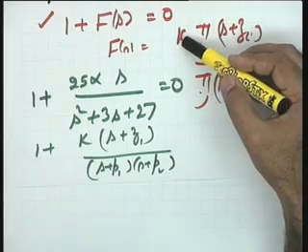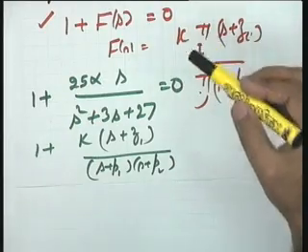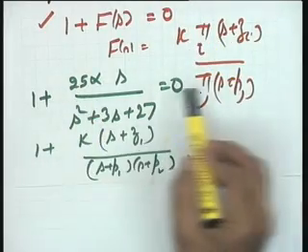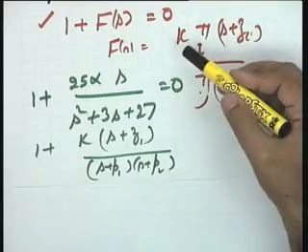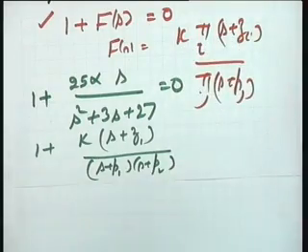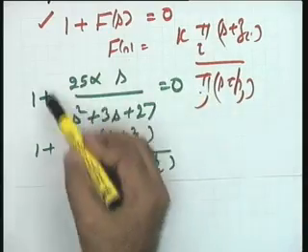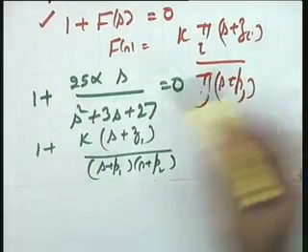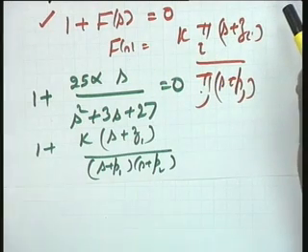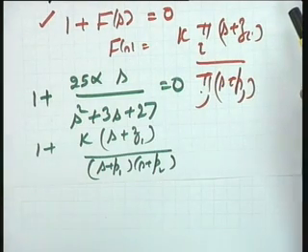And now this K, which I have referred to as the root locus gain, is nothing but 25 alpha. If you make a root locus sketch, as K is varied from 0 to infinity, accordingly by a scale factor of 25 you can get the numerical values of alpha from the root locus plot.